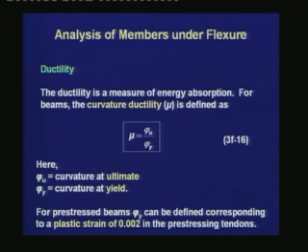corresponding to the defined yield point. Then we can have a value similar to 0.87 fpk divided by Ep plus say 0.005, which gives a plastic strain of 0.005 for the defined yield point. Thus, the definition of yield point for a prestressed section is left to the analyst based on how much plastic strain the analyst wants at the onset of yielding.